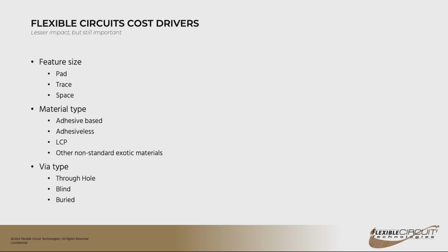because when you're doing sequential laminations, you're building until you're about 80% complete and then go all the way back to the beginning and run it back through again. And of course, each time you do the cycle, there's going to be fallout and yield. So having many different via structures will have a huge impact on the cost of your circuit.